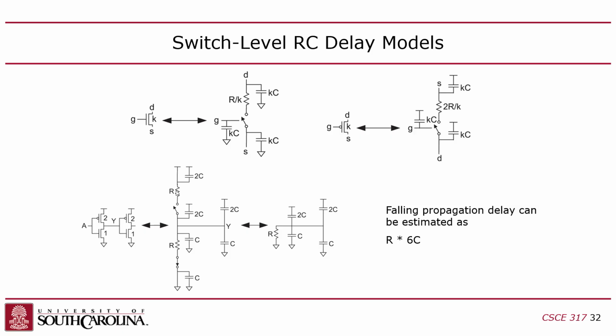Well, remember, you have to consider the state, though, right? So in this case, check this out. I am setting the input to 1. A is 1. What does that do? Pulls the output down, right? Because I'm inverting 1, I'm going to put out a 0, right? What does that mean? It means the NMOS is on, the PMOS is off, okay? Under this condition,